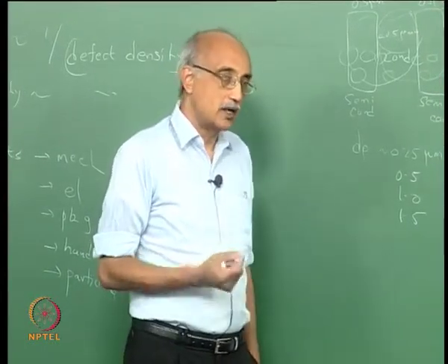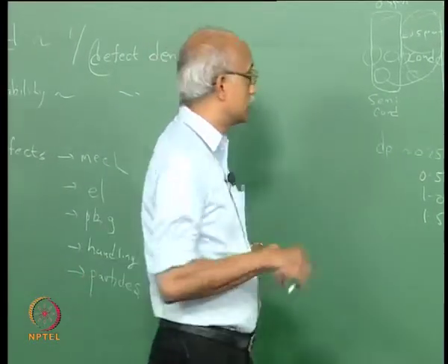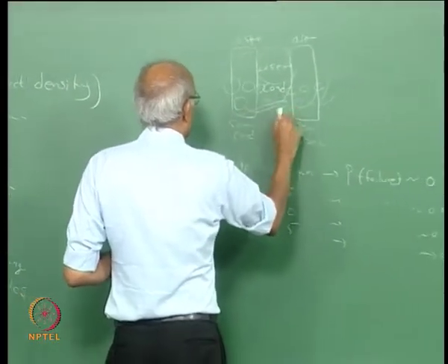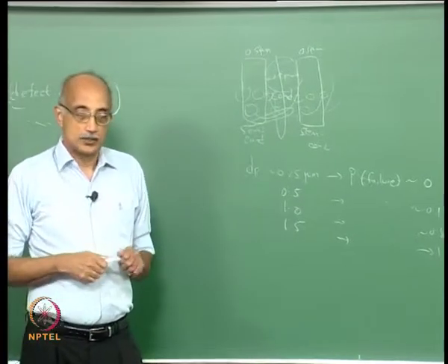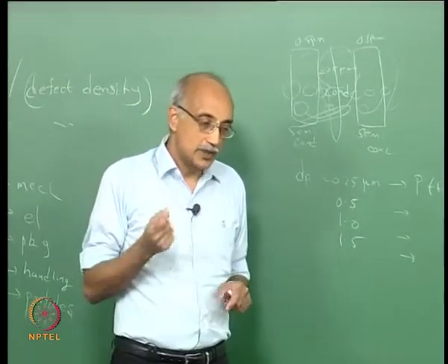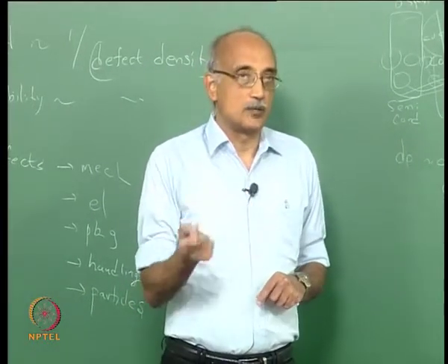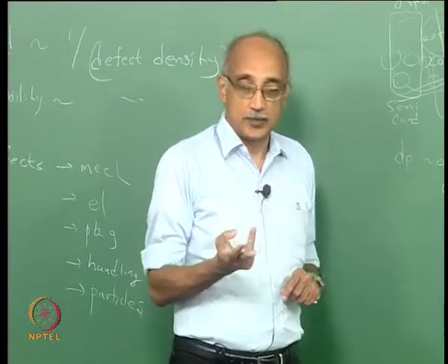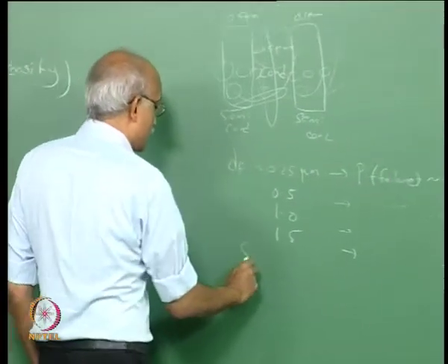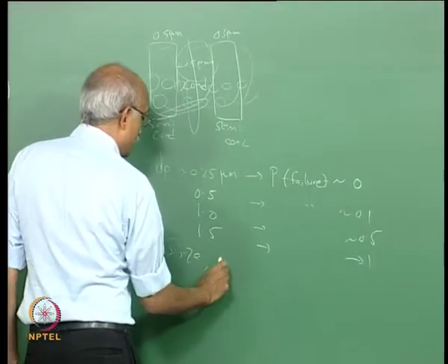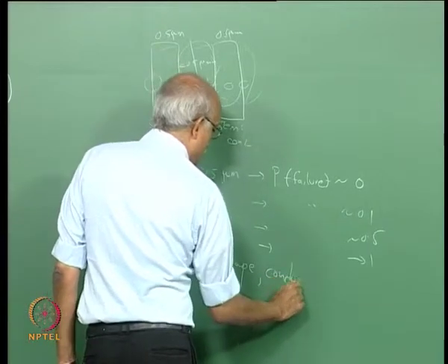But if a particle is highly non-spherical, then you can have much larger particles that are present, but if they happen to be in a certain position, they won't cause a failure. So interestingly enough, a spherical particle is more likely to cause a systematic failure compared to a non-spherical particle, and so shape plays an important role as well. So there are at least 3 characteristics that are of importance here that we have discussed at length earlier in this course.